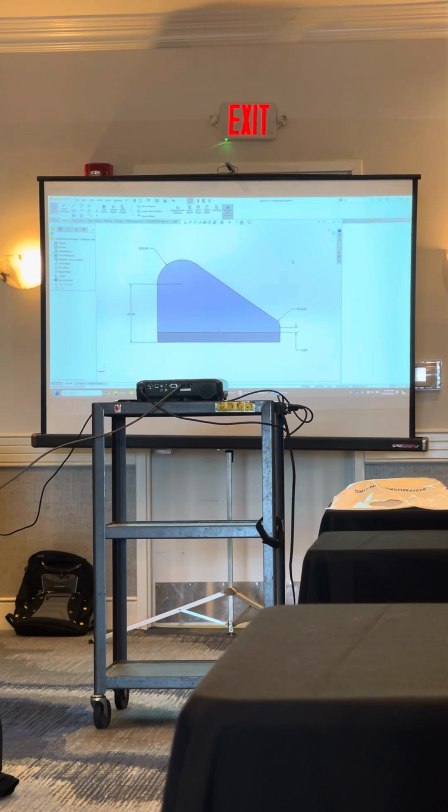And then when I teach sketches, I go through 3 distinct phases. This is good for you guys teaching other people. First phase, get the geometry on the screen. You need a rectangular shape, get a rectangle shape on there. You need a tombstone shape, you need a shape, whatever it may be, get it up on the screen first. Don't worry about angles, don't worry about size, don't worry about any of that.